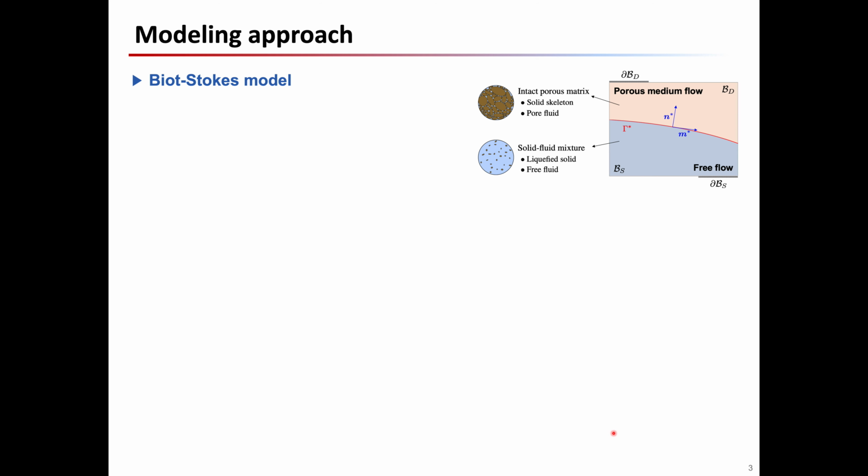A model that simulates coupled hydromechanics in vuggy porous media is called the Biot-Stokes model. It adopts the Stokes equation to model the free fluid while using Biot's poromechanics theory for the intact porous matrix. This Biot-Stokes model is the starting point of this study.